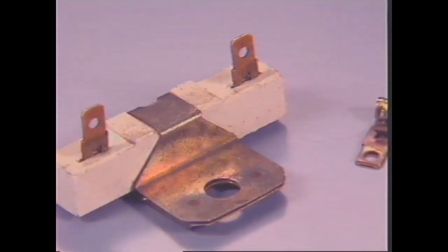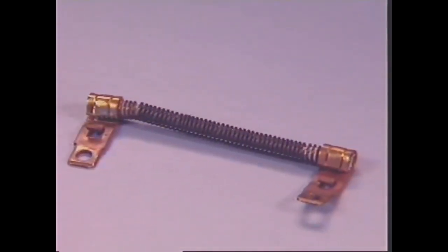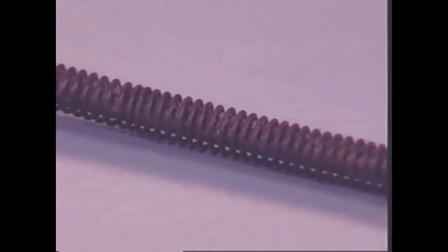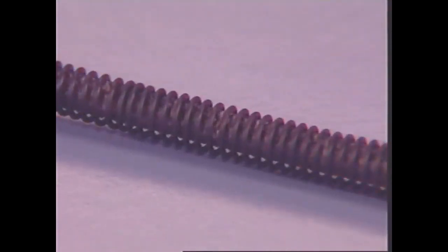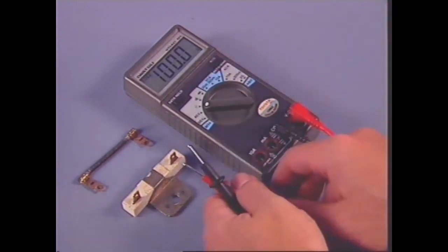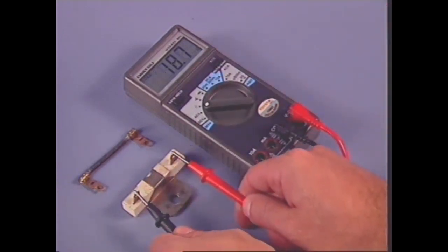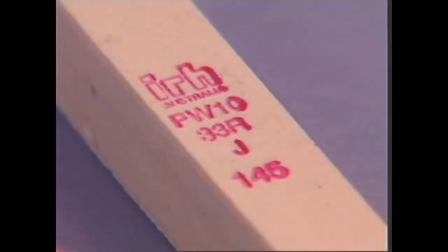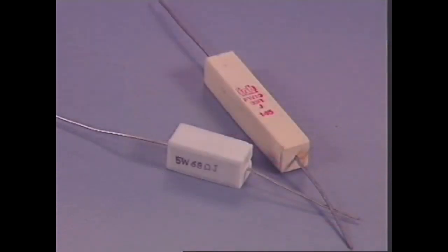Most resistors that can carry large currents contain a coil of high resistance wire wound around a ceramic former to dissipate heat. Resistance is measured in ohms, represented by a Greek letter omega, and so resistors are rated in ohms as well, to indicate how strongly they will oppose any current flowing through them. Resistors also have a wattage rating. This is because resistors work by converting some of the electrical energy passing through them into heat.